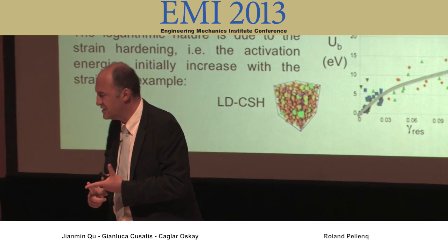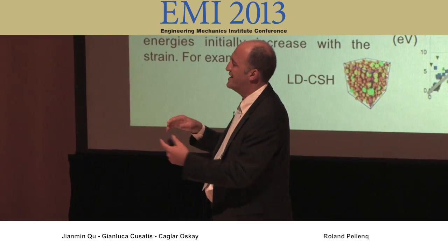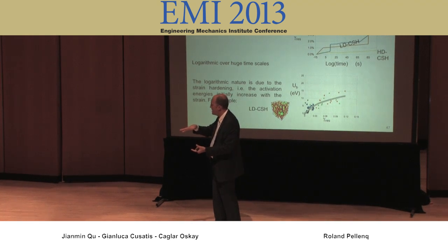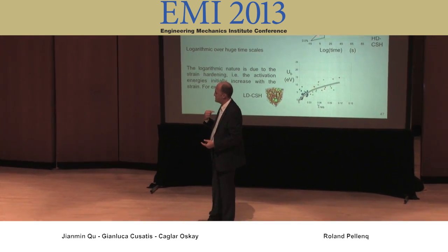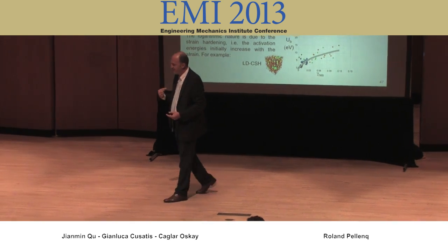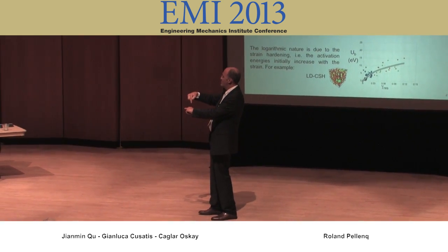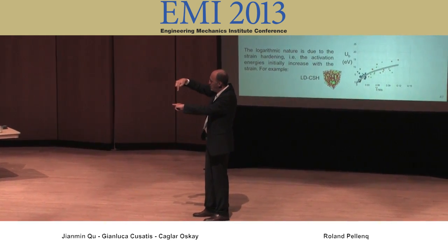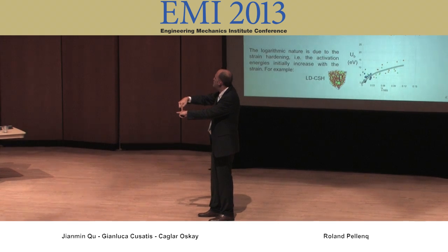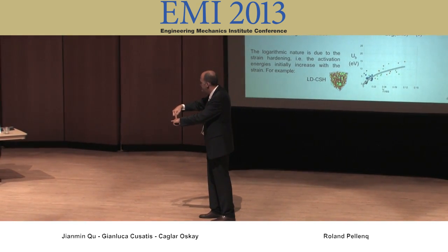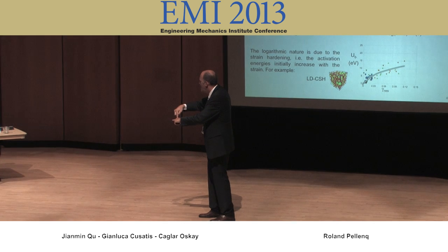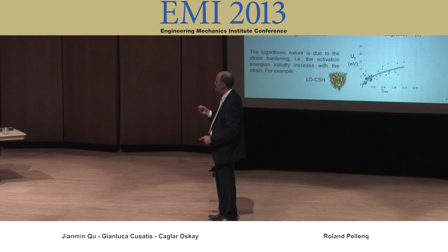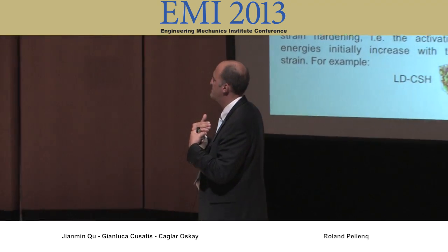Second part of the question is about the nano indentation, the way we calculate it. We calculate the elastic property of the box, just like we would do with atoms, at equilibrium. So there's no rate in my simulation. Why is this? Because the experiments are slow. The way the tip goes into the system is very slow compared to any atomic process or any mesoscale process anyway. So for us, if we want to compare to experiment, we do not want to have a rate. We want to be at equilibrium, at least at the scale of our simulations.